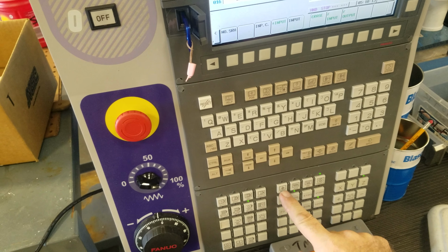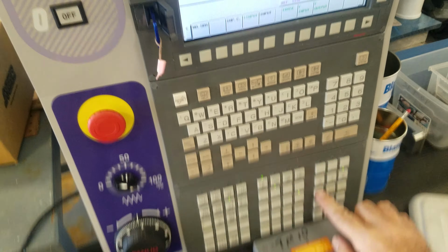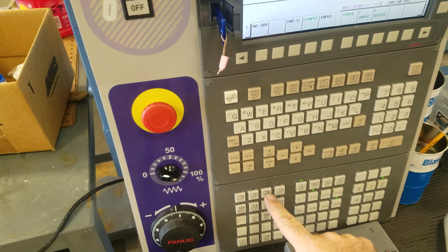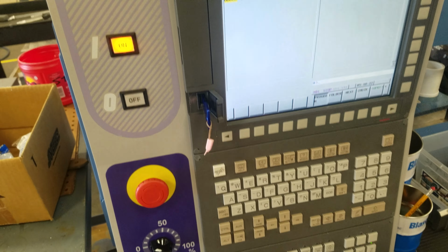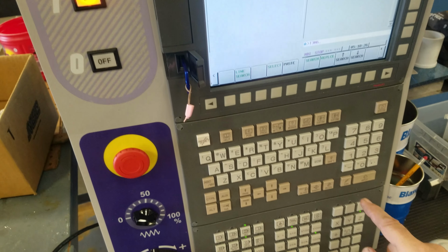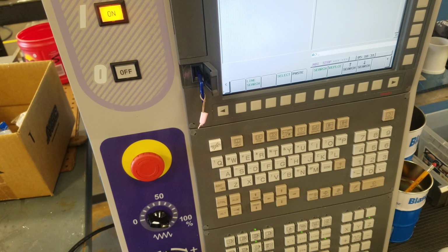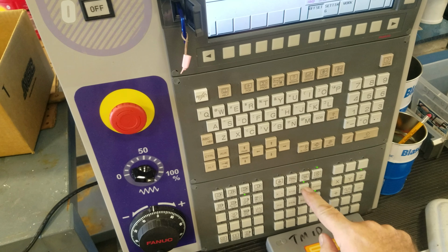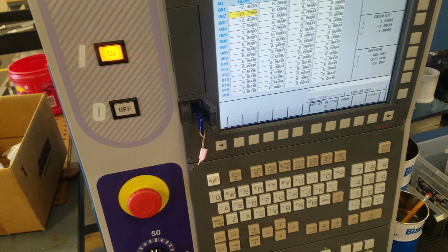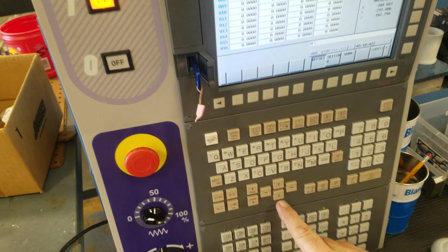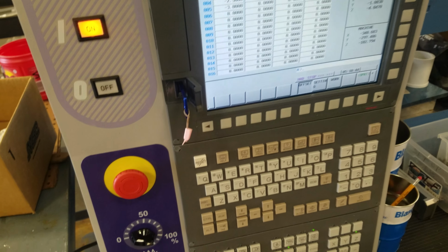Now to get safely home, if I do reference Z and press the Z, I'll go right to home. Then I go back to MDI, program, get the next tool, tool 3, M6, end of block input. Cycle start again. Tool is now changed. Go back to offset, handle, Z, big number, bring that one down. Go to 1,000th, get closer. Make sure you're on the number 3.